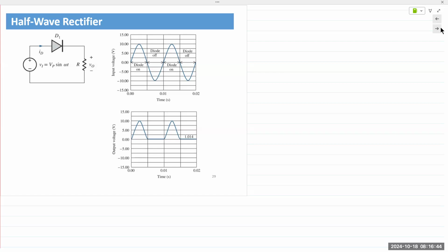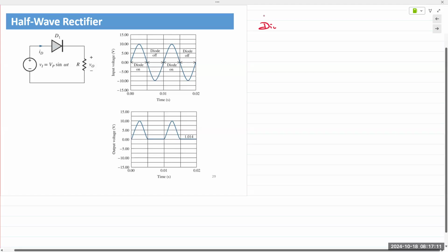From this point on, we will look at diodes with AC as well as DC signals, meaning we would apply a DC signal to bias the diode at a certain point, and then apply an AC signal on top to see how it would deal with it. And so it modifies the AC signal, meaning it's shaping the waveform. Hence, these circuits are also known as diode wave shaping circuits.